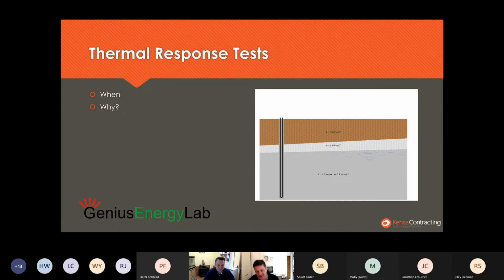Why would we do a test? So this is an example of a ground condition that we might find. This actually is what you tend to find under London. It's called the Thames sequence. And on the top here, you've got the London clay. You've then got the Woolwich and Reading beds and Thanet sands beneath, and you've got the chalk underneath.